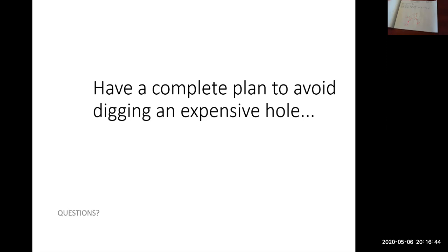You could sketch out where that excavation is going to be. So if you drew that to scale, if maybe there was a building that was 2.5 meters away, you could determine that your excavation would be underneath that building if you use one-to-one slopes. So that would tell you that you would have to do something different in order to protect that building.